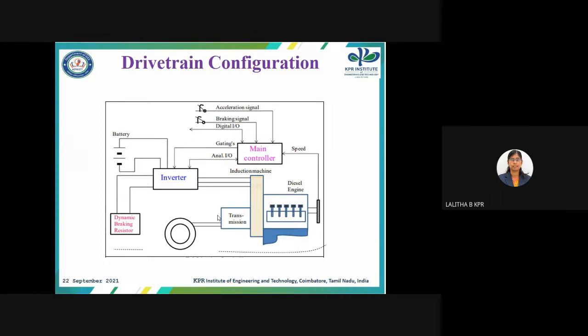The next one is high IC engine speed. When the speed is high, the torque assistance control is performed as in the medium speed range. In battery recharging control, the induction motor output power is kept constant.